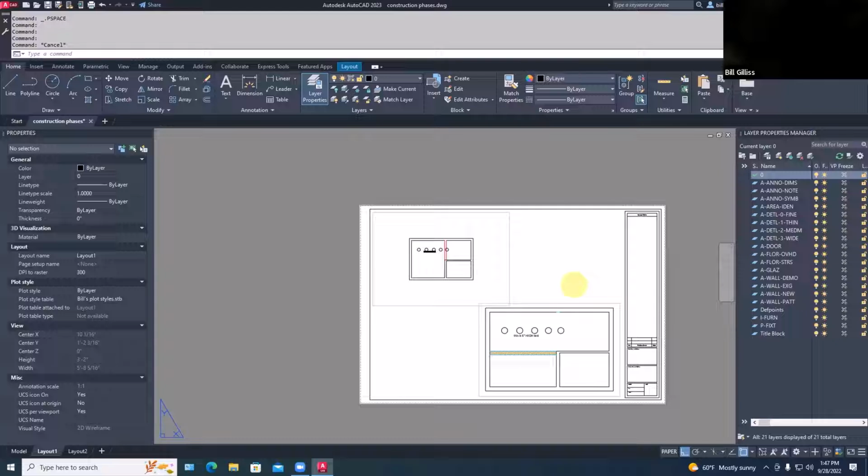Annotative text gets relatively bigger as the scale gets smaller, and it can cover up something that was right next to it. In any big firm, there'll be some CAD manager who will figure out this is how we're going to do this and puts that in their template and they use it, but it's still a pain to deal with. You might not know ahead of time at what scale you're going to plot a particular view. Therefore, you sort of can't pick a style to start using.